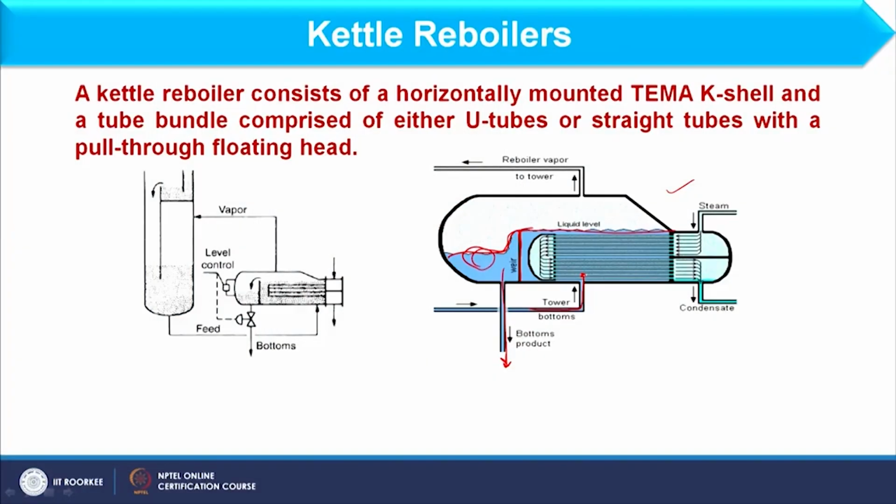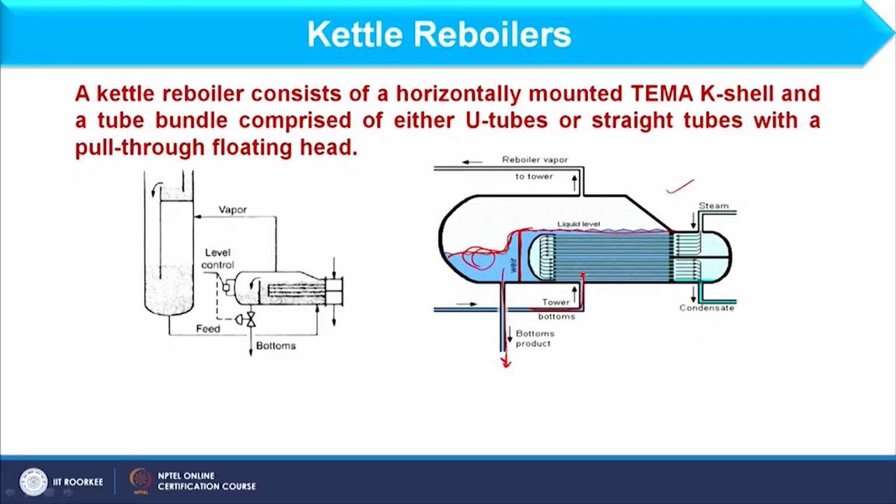Fine. Now, as far as shell and tube heat exchangers and condensers are concerned, there we have discussed that baffle placement is different in both types, either it is an exchanger or a condenser, okay. So, when I am focusing on the reboiler, we consider baffles in these types of exchangers also, okay.